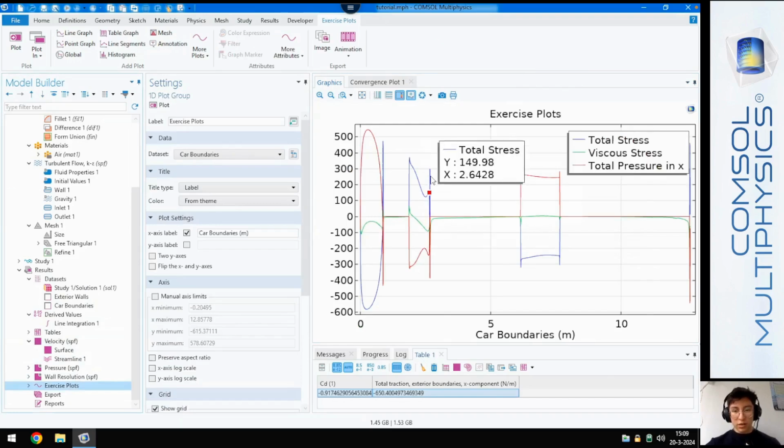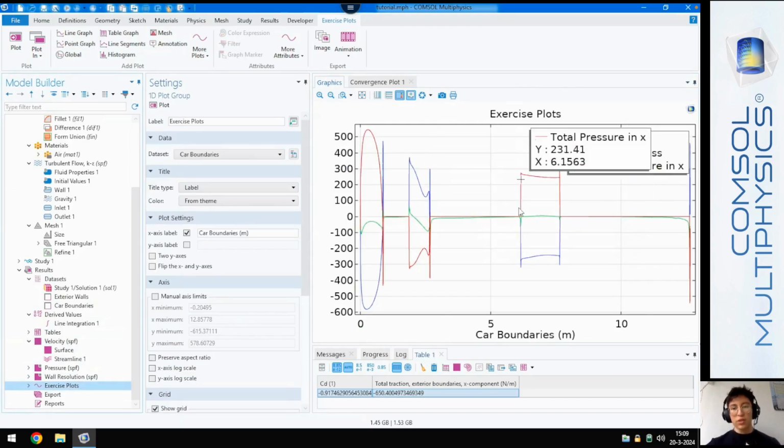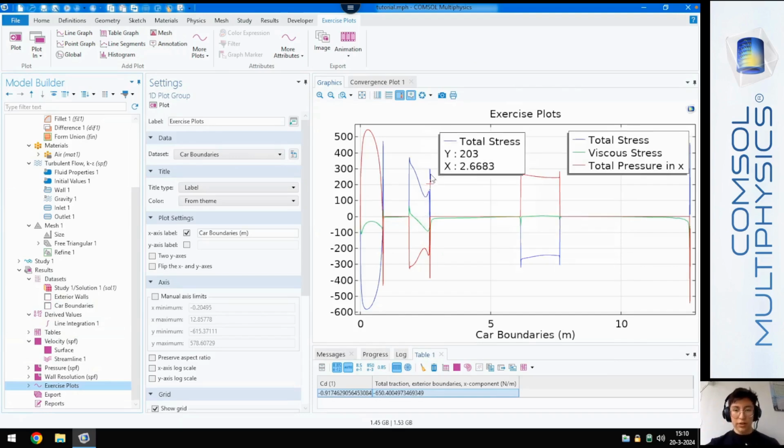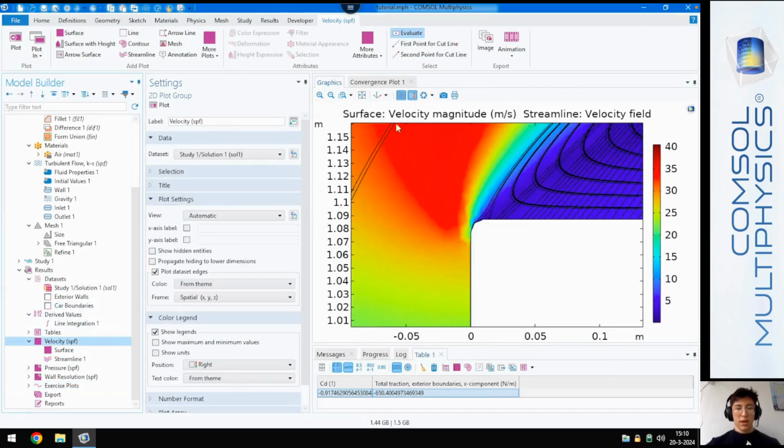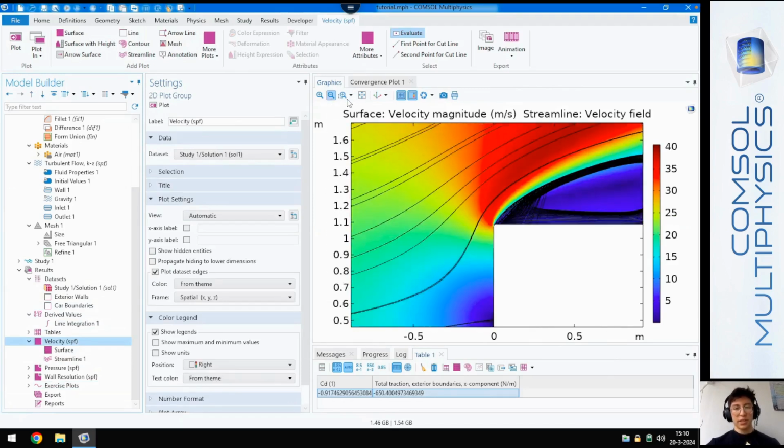And that is why you're going to have these spikes here. All these spikes are usually caused when there is a boundary or where there's a fillet. Anyway, so where there's a vortex or where there's a fillet. The fillets usually make the effects less anomalous because the flow can just bend around and it doesn't hit a hard edge. But generally, that's what these big points mean, that the air is encountering a sharp change in the geometry of the car, which makes sense. And yeah, that's basically it.